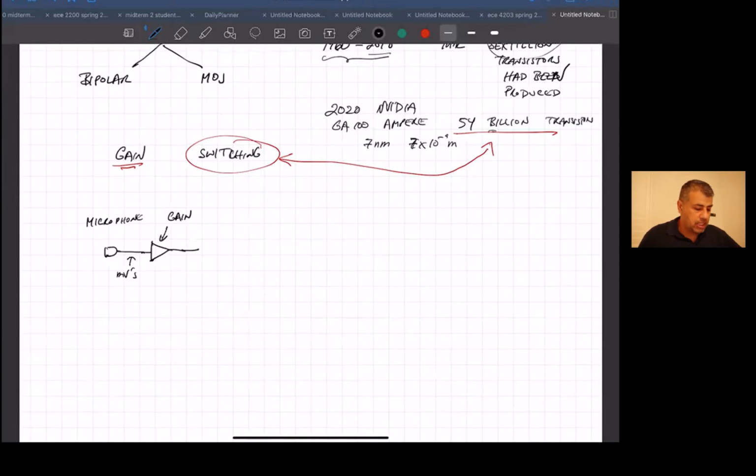So what you want to do is modulate this gained-up microphone signal with some kind of 1 to 2 gigahertz signal. That's the signal frequency. You're modulating the audio with that frequency so you can use a shorter antenna. It's usually 1 to 2 gigahertz, depending on the cell phone standards that you guys are using. Of course, this is a very, very simplified signal path.